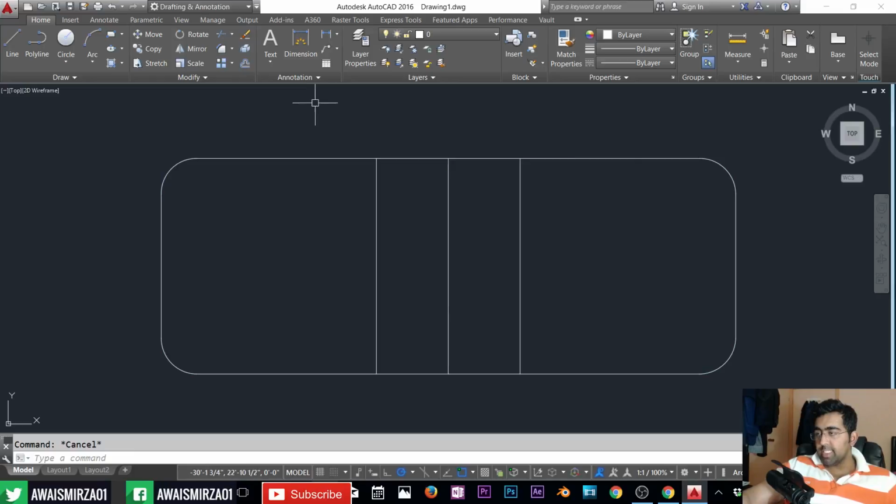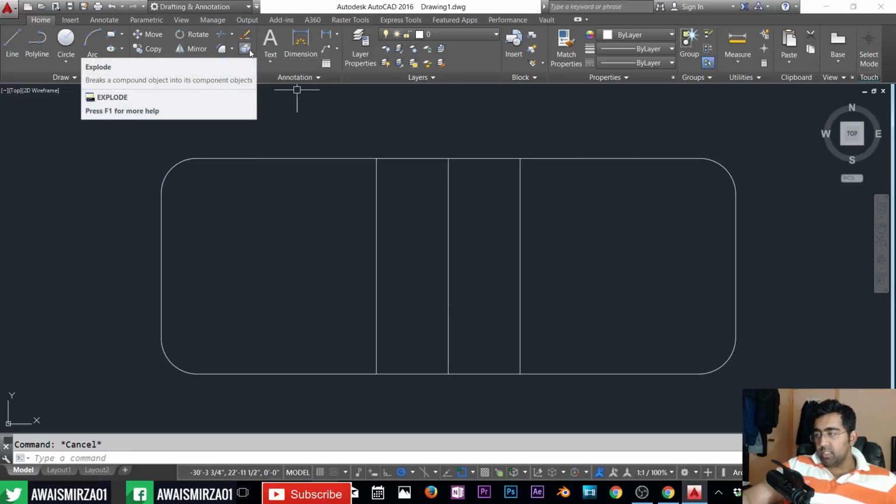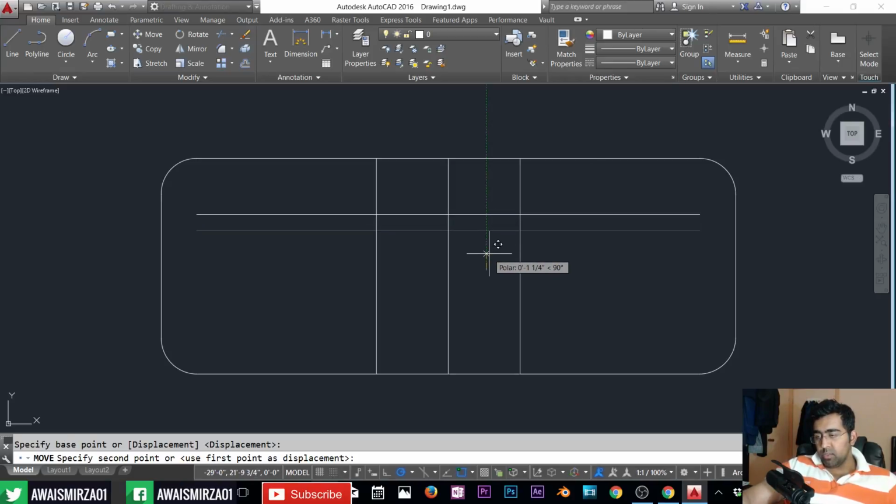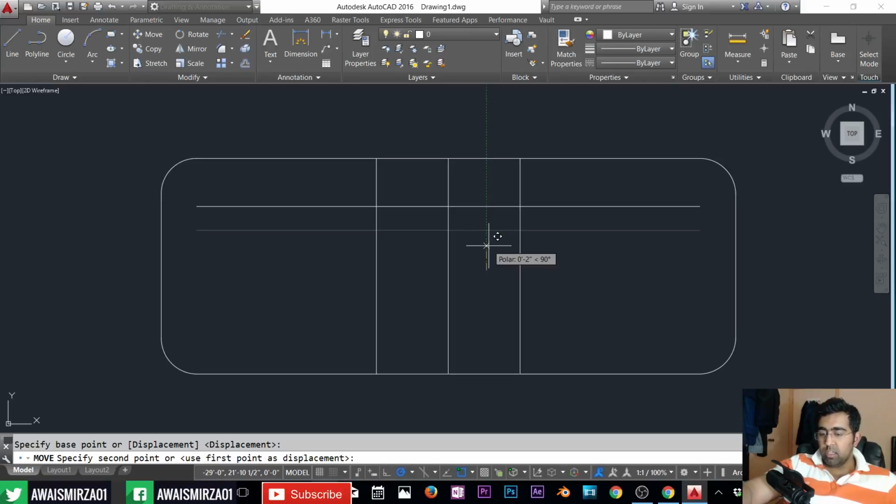Oops, I need to draw another line. For that I can explode that actually. So this is the explode command, select that, select this polyline, press spacebar. Now we have separate objects, separate lines, right? So now let's use offset. O is a shortcut key for that. I'm going to type 6 inch and then down, and then from, yep, that's fine here. Maybe we can move this up actually to about 3 inch.